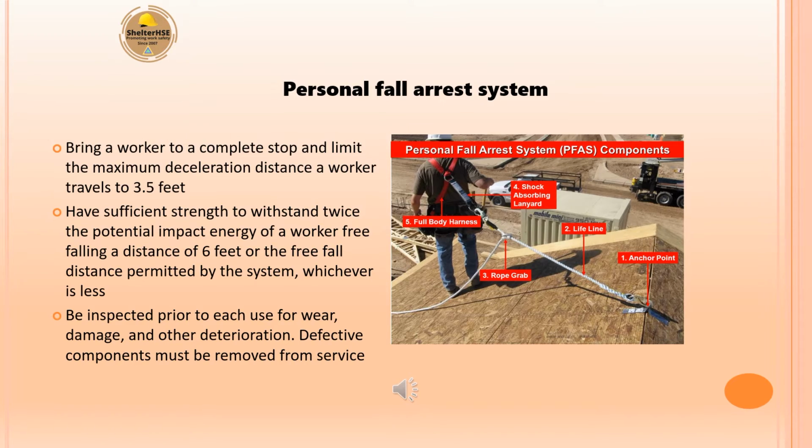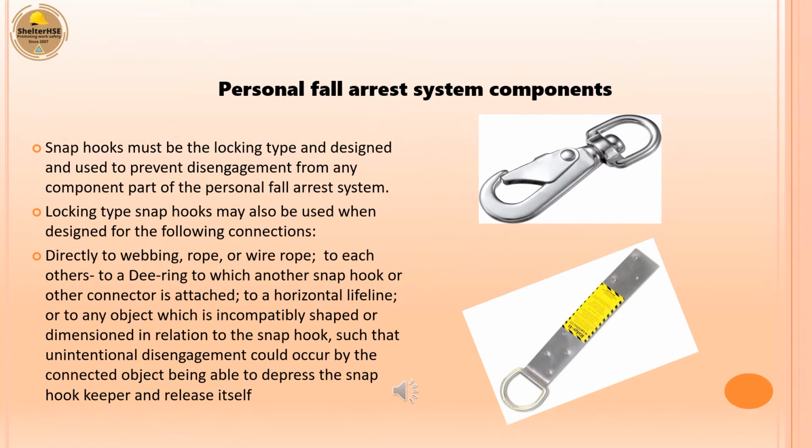Snap hooks must be the locking type and designed and used to prevent disengagement from any component part of the personal fall arrest system.